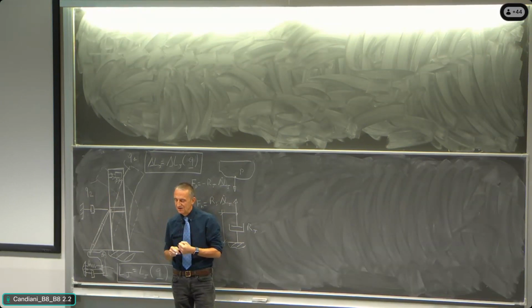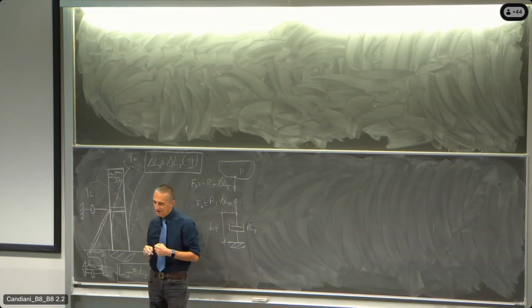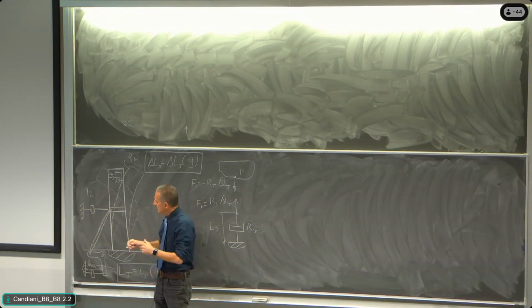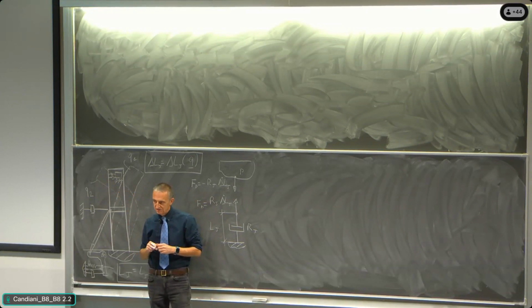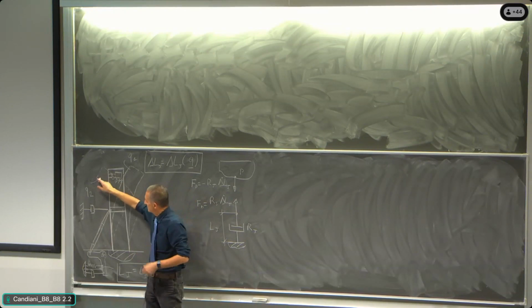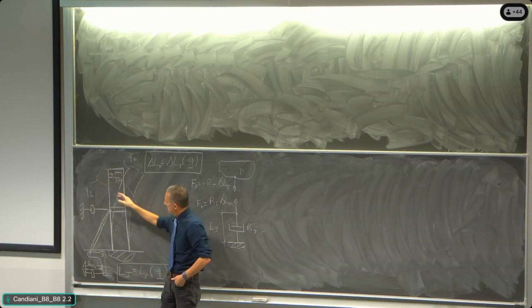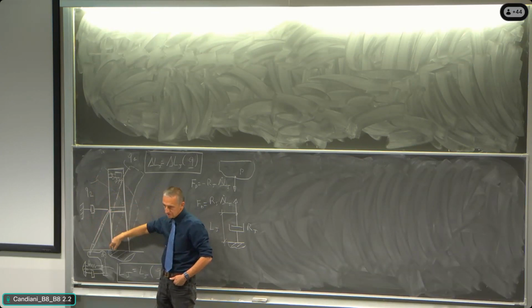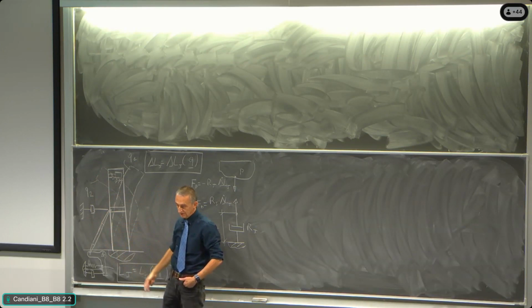So what do we need? We need that the action given by the damper is able to make a lot of work on the mode, on the modal displacement, on the local modal displacement of the point in which it is connected. And so it will be very effective if it is positioned in a location that is moving a lot within the mode. And so the modal shape close to the connection is totally not effective. If I am positioning a damper down here, it is absolutely wasteless.